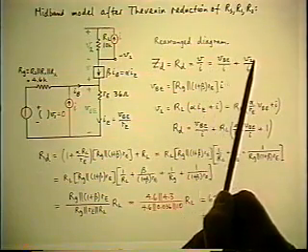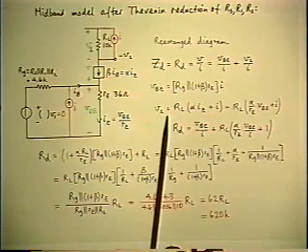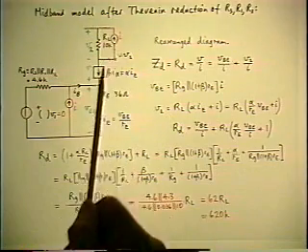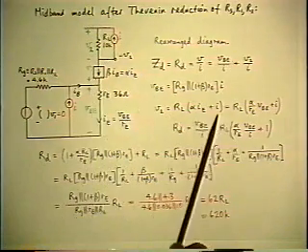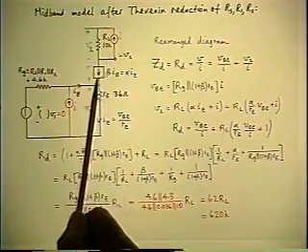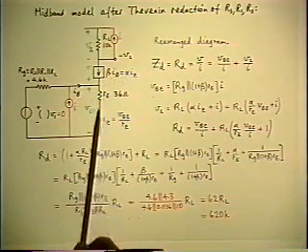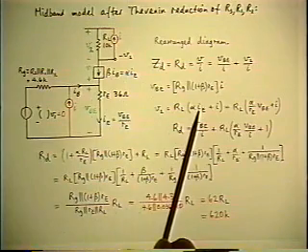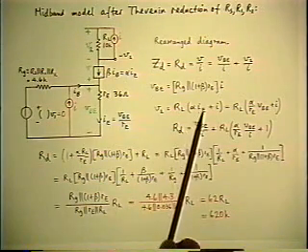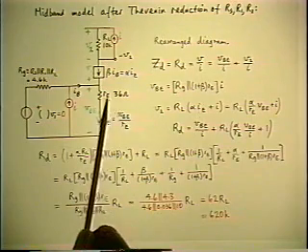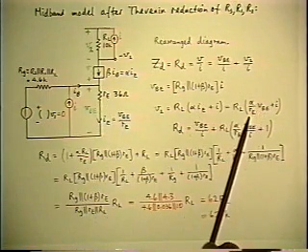Now I also need to know what is V2 as a function of I. V2 is the voltage across RL, which is driven by two current sources, one of which is I, and the other is the collector generator beta IE or alpha IE. Same thing. But the IE I can find in terms of the VBE. IE is VBE over RE.